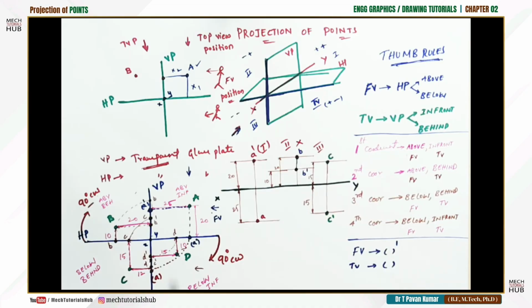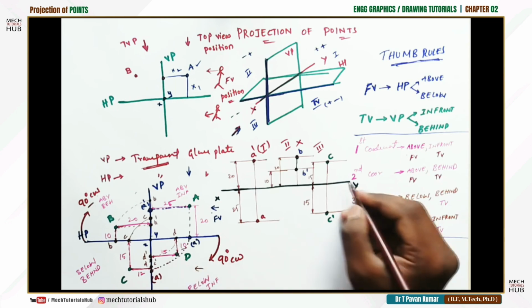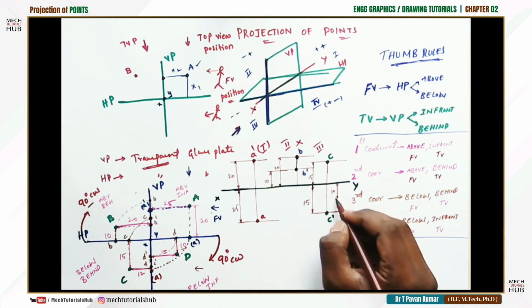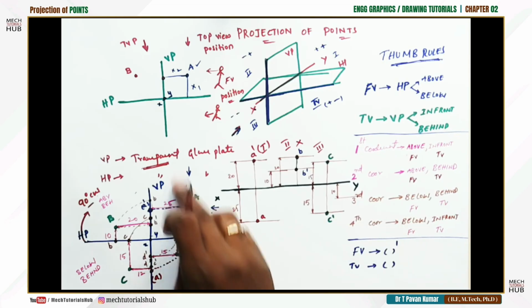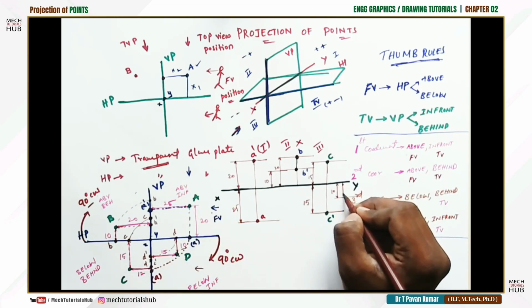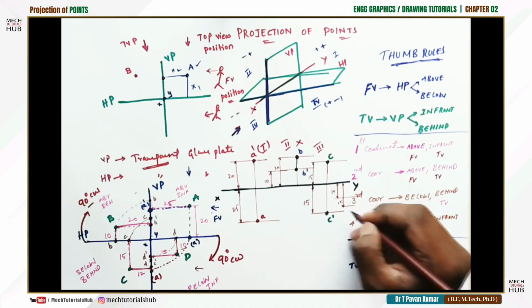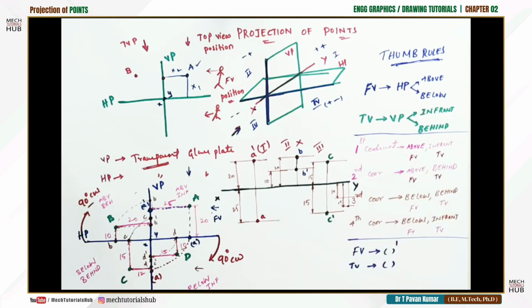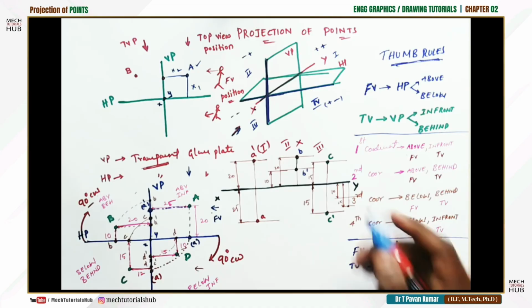Okay, let us draw on an XY line. Now what is the distance? 10 mm below HP. So from here I'll make a mark of 10, draw one locus. Similarly, when I view from the top, 15, so at a distance of 10 mm, I'll draw a 15 mm line also. Okay, draw one locus, and at a distance of 10, one more point, draw a projector line. Now wherever that projector line meets both the loci, enlarge or darken your point.